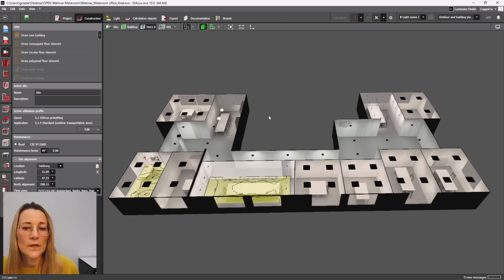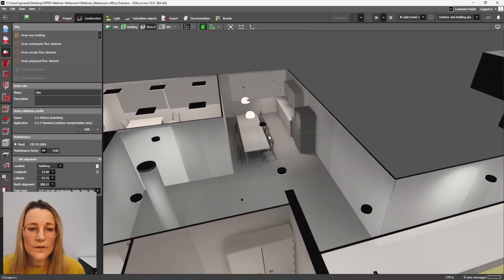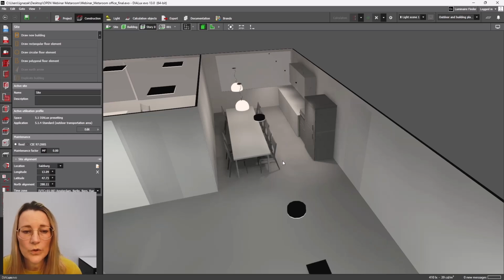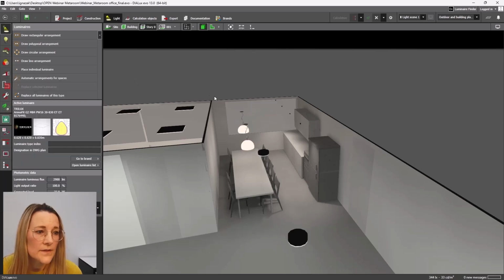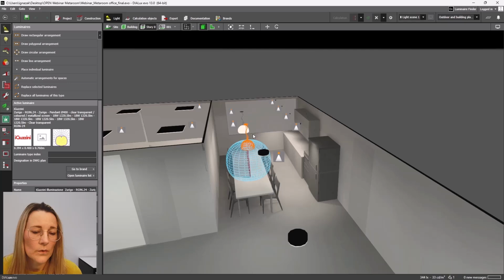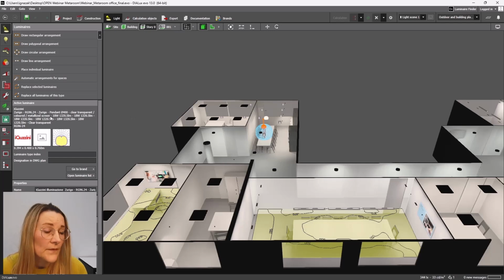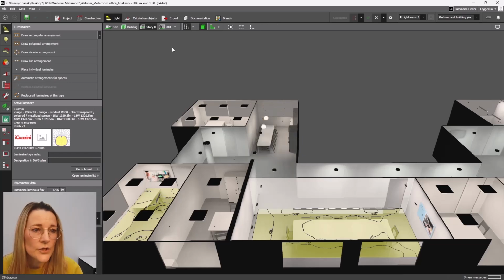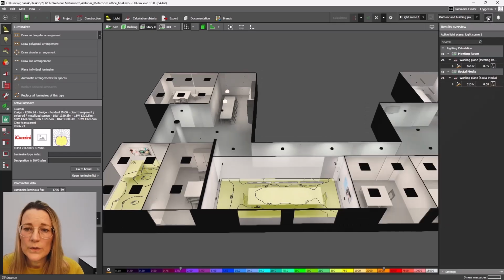And you can see I've done the lighting design for all rooms and decided that I want to check the working plane in some rooms, or here's the kitchen area. So I have seen that before on the snapshots and got the information. And can go forward with the perfect lighting design, for example, here, or only on some luminaires. So I can check this too. We have different possibilities for the export. So maybe after the calculation, we can export some files. I will show you the result overview too.